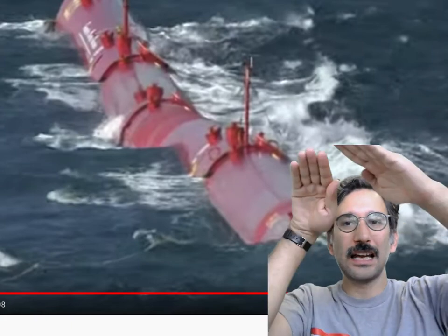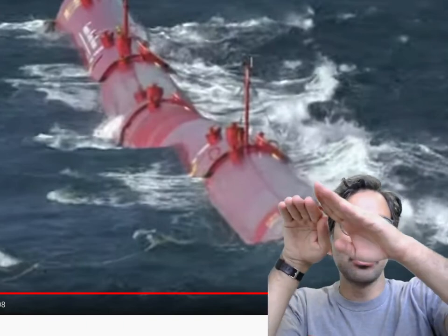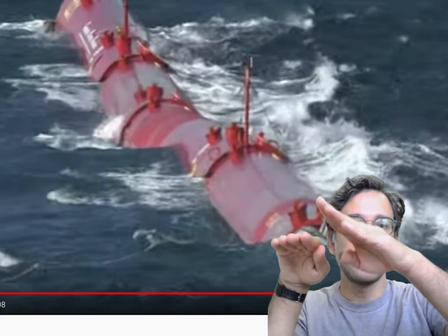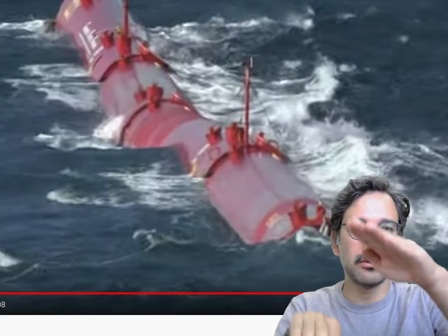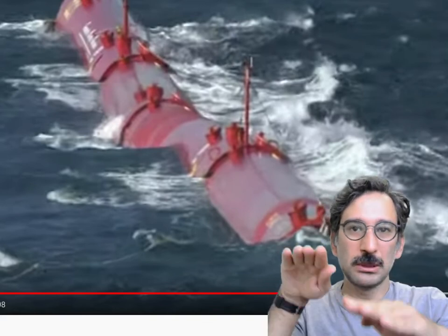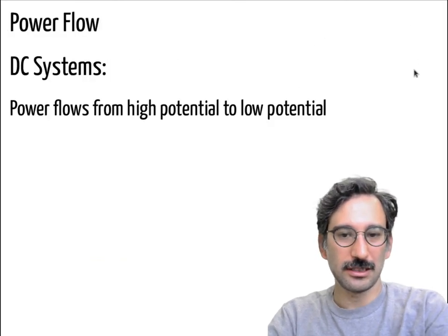If the device is moving at the same time as the waves, there will be no force. In other words, there will be no load angle, and if there's no load angle, you cannot generate any power. In order to generate power from the waves, the movement of the device has to have some phase difference with respect to the waves. So you need to really understand that one.